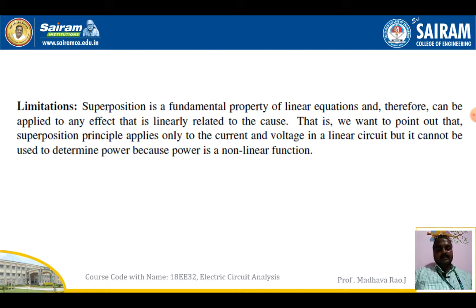Finally, what we can say is that the superposition theorem is applicable only to linear circuits and linear parameters. Current or voltage values we can find, but power is a non-linear quantity, so we cannot find it using the superposition theorem. Power values will not satisfy the superposition theorem.